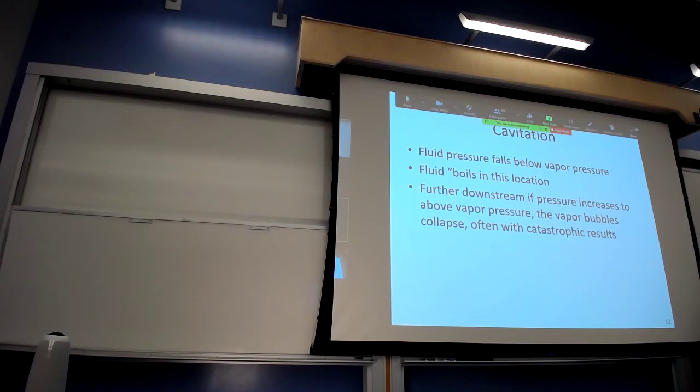If you've ever taken a garden hose, and when it was flowing, you crimp the hose, and you hear the water moving inside, hissing at you, you are boiling that fluid. The hissing you hear are the air bubbles. And what happens is you created this zone where the pressure is below the vapor pressure, so all of a sudden you're boiling the fluid at ambient temperature.